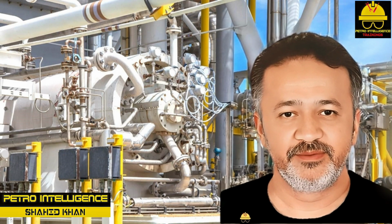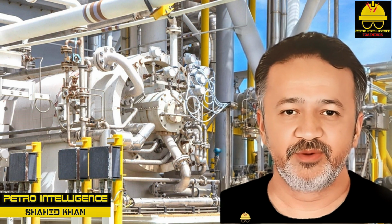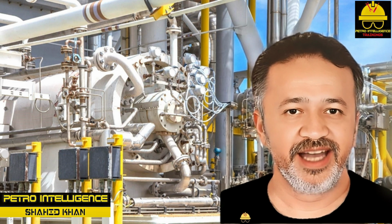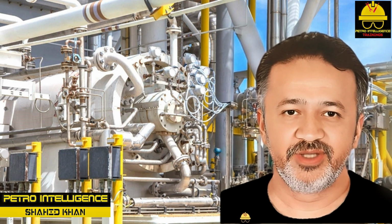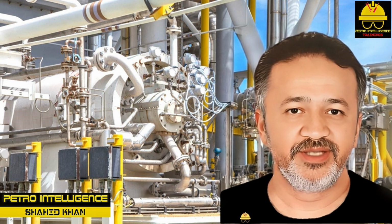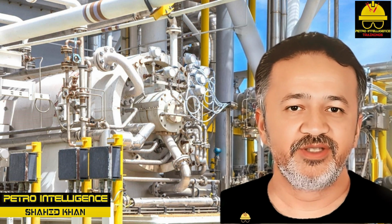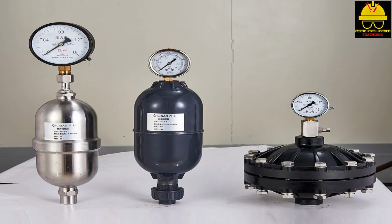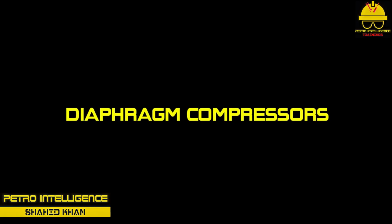Pulsation control. A common problem found with reciprocating compressors is pulsation. This inherent problem occurs because the suction and discharge valves open and close during each cycle. This problem can be controlled by using a surge drum, pulsation dampener as shown in picture, or volume bottle. These devices provide smooth gas flow, reduce vibration, and prevent overloading or underloading the compressor.